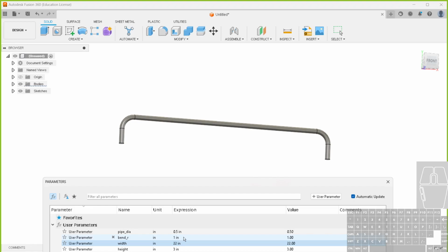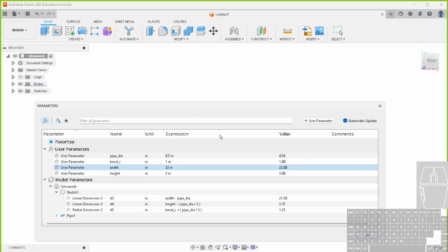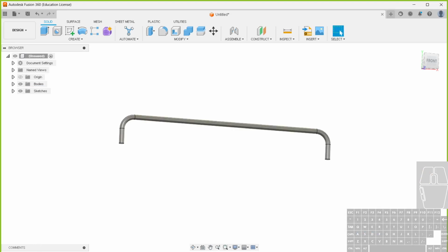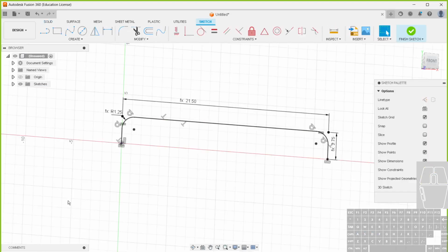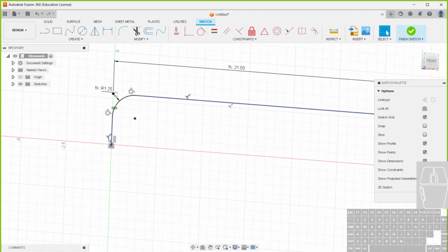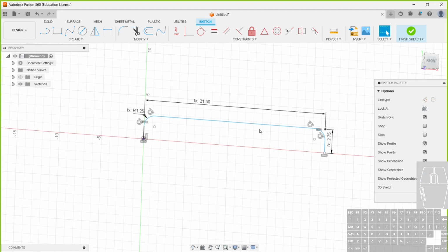When doing 90-degree bends, how does this work? Does it still do it? Yeah, just instead of on your sketch, instead of making it perpendicular, it'll still do the calculation. Well, we haven't even gotten to that stretch out part yet. But instead of doing the perpendicular here, maybe instead of doing that one vertical, I'd take that off and I'd make this one horizontal. And now I can dimension here to here, leave that 90, dimension that one to there, make that 90.